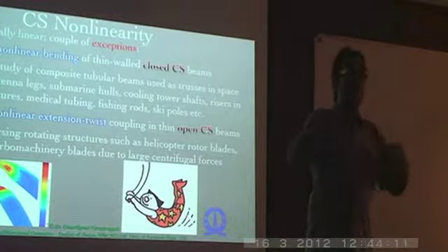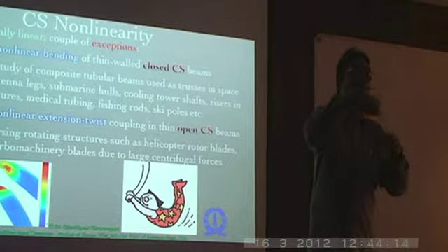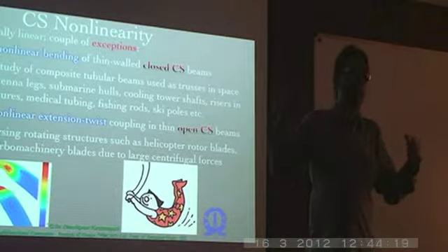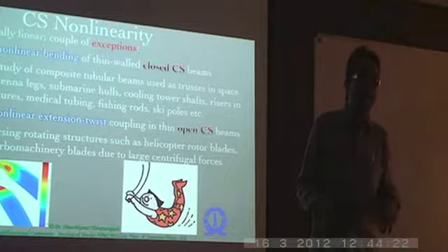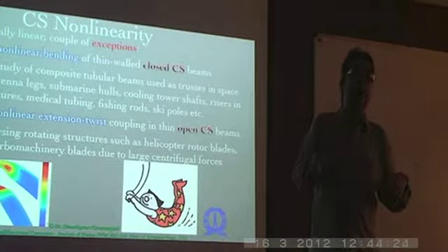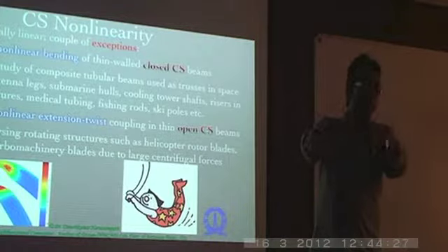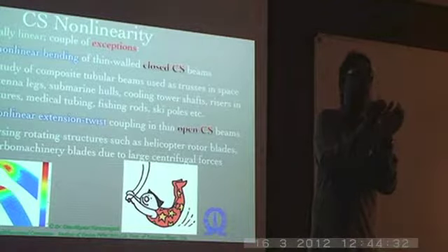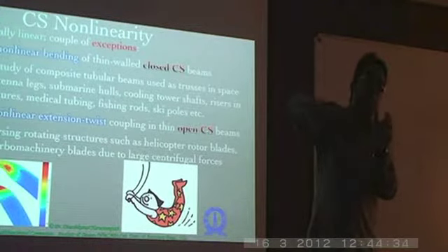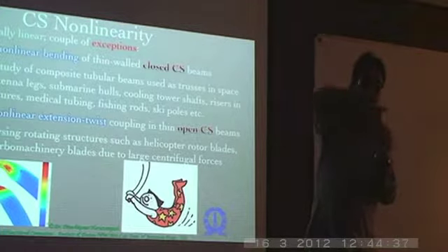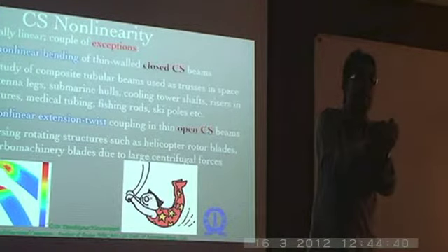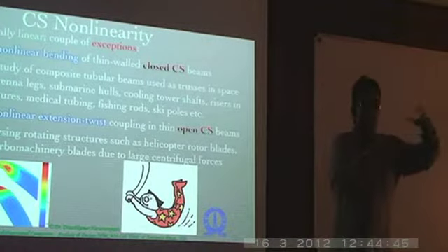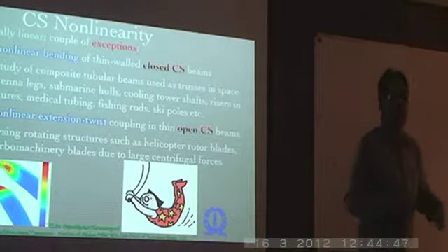Okay, but otherwise, if it is a concentrated load, then there can be a lot of local effects which are taking place, and those are entirely three-dimensional. Yeah? Any beam theory, even asymptotically correct beam theory, will not be able to handle something like that. So in such situations, what you have to do is a 1D analysis for the entire thing, and in that local region where the concentrated loads are there, you might have to do a local 3D analysis, using the results of your 1D analysis for the rest of the structure to give the boundary conditions for that. You can do a local 3D analysis for those regions. But usually the case doesn't occur because of this diffusion through the stiffeners.